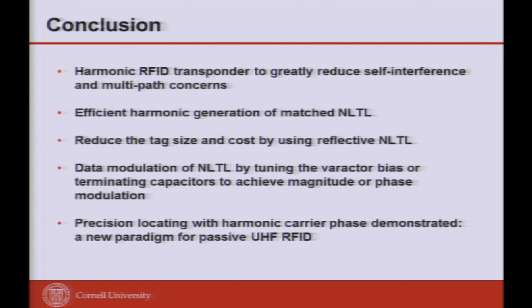So that is well suited for ranging purposes, and you can design a nonlinear transmission line to be very high frequency on an integrated circuit platform. As I mentioned, you can also do it on PCB, at 900 megahertz and 1.2 gigahertz. People have built a lot of these for instrument reasons, so these are well understood, and there are interesting applications to ranging.